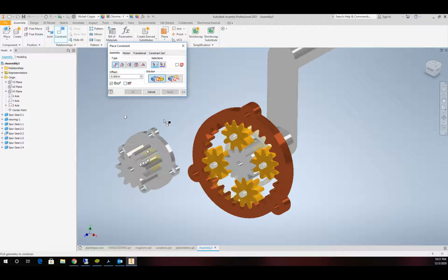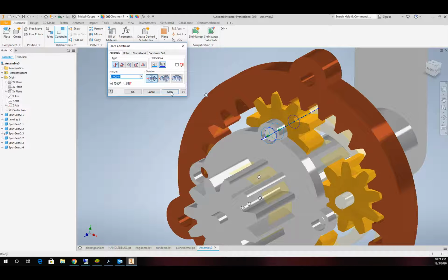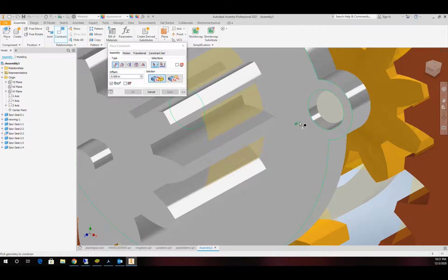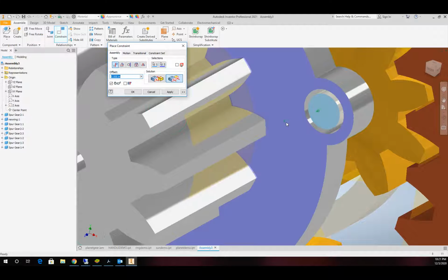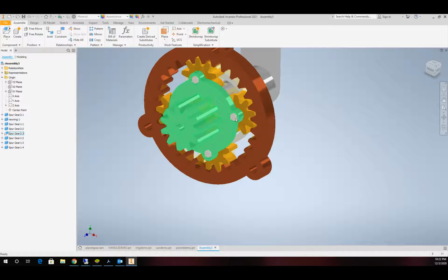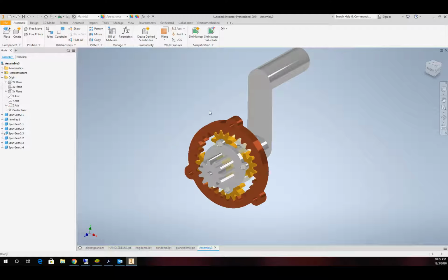So to do that, I'm going to use a constraint, and we're going to do an axle constraint to one of these shafts. We'll do it on the second shaft. That should keep it in alignment. Okay. And then finally, I'm going to do the face of this with a flush to this face here. Now I've taken care of, with 3 constraints, adding the planet holder to the new sun, and that'll give me my best chance that the Dynamic Sim will automatically weld those parts together for me.